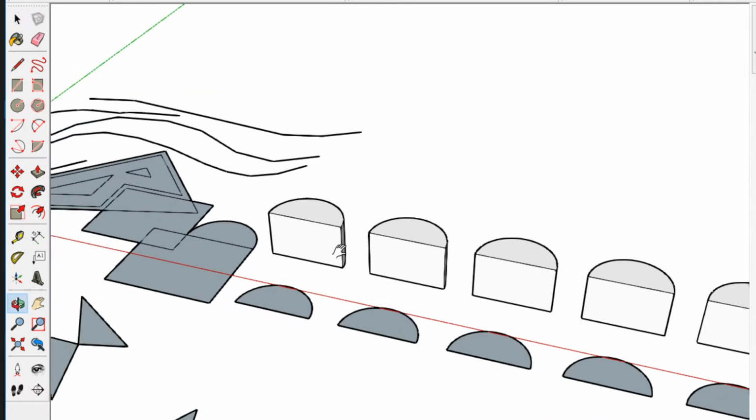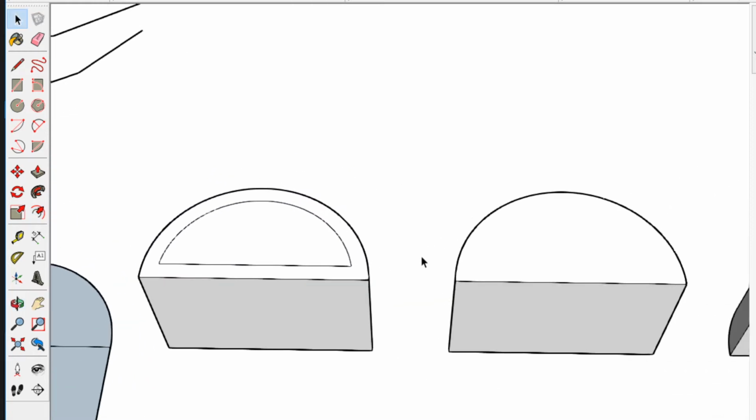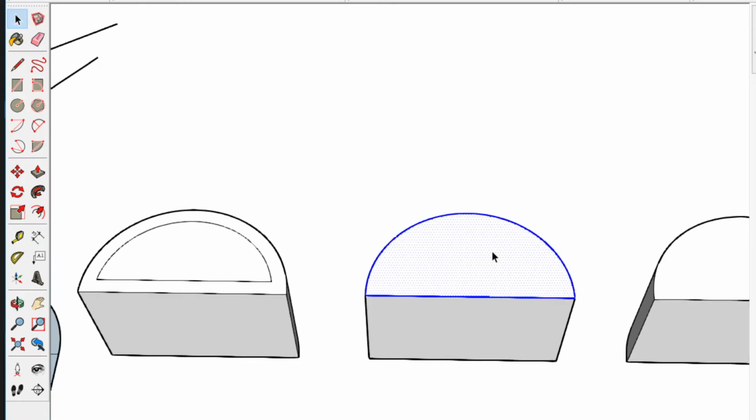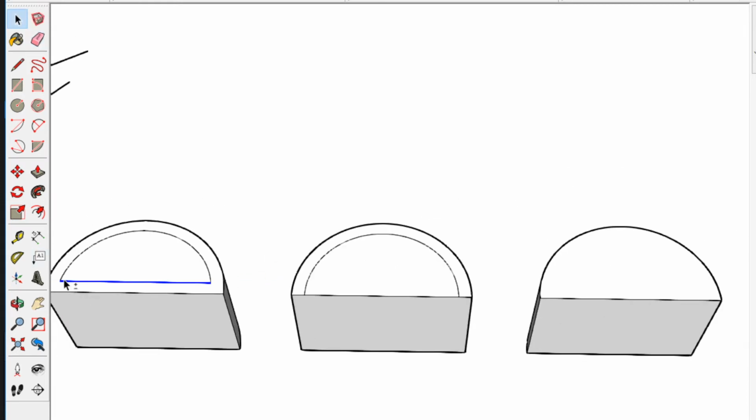That's pulling. How about pushing? Let's say offset, letter F. Okay, F, chuck. Or another way to offset is to select first, deselect these two, remember, right to left, and then offset. So I don't have to delete this one and draw a line and draw a line.